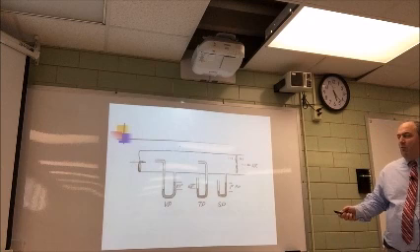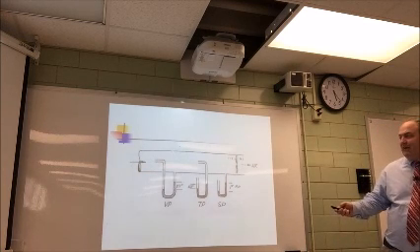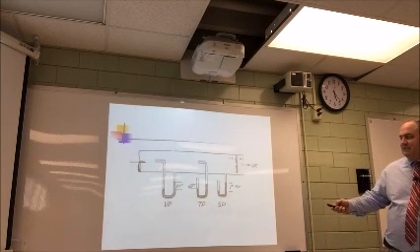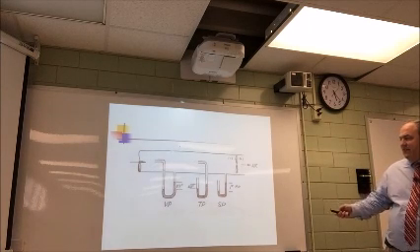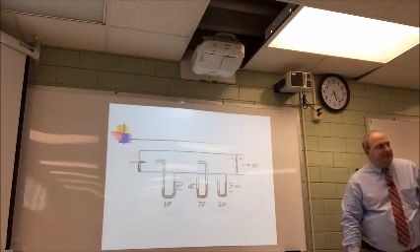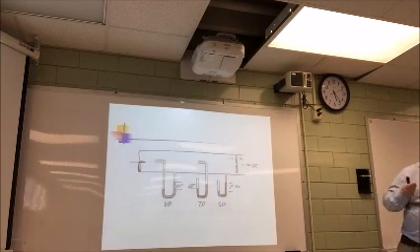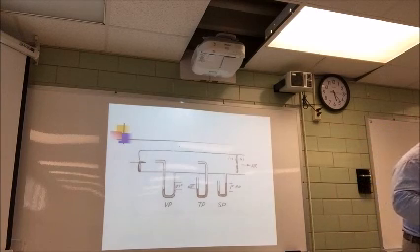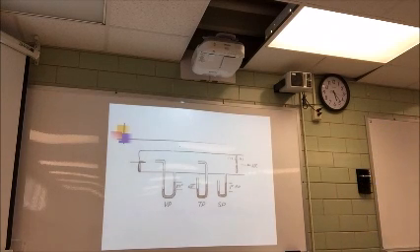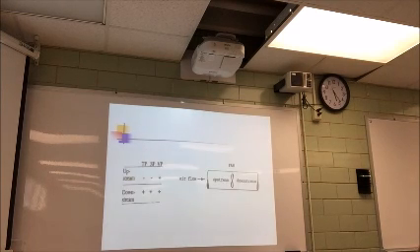Yeah, 0.7. What I tried to do with this diagram is give you, this is giving you velocity pressure, this is total pressure, and this one's giving you static pressure, okay? So I tried to give you a visual representation of what we're measuring. I know this is one of those concepts that's like, well, it doesn't make sense. Yeah, think about it, it does. Your total pressure is static pressure plus velocity pressure.